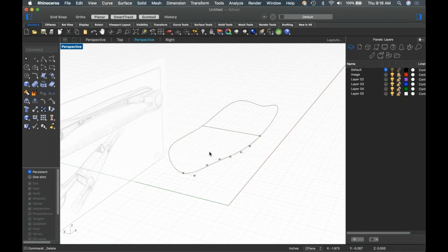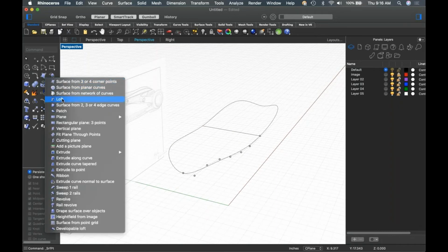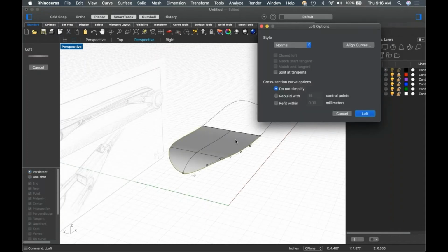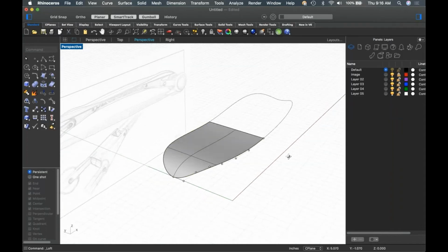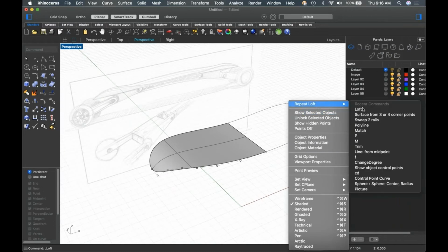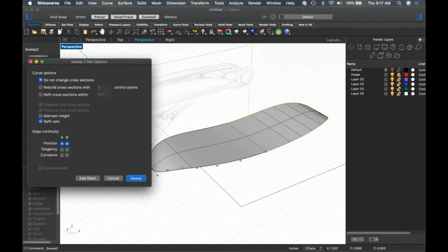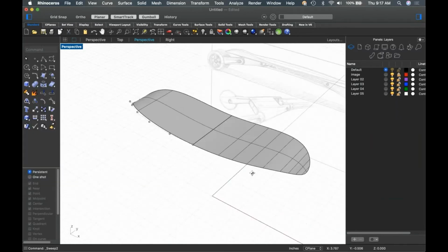And I may just go ahead and roll with that. The other thing that I could do is I could actually just loft this side to side, because it just gives me the exact same thing. And loft might give us a little better result. And you can see the difference between sweep and loft. So when I swept it, look what happens. See how complicated that surface is?